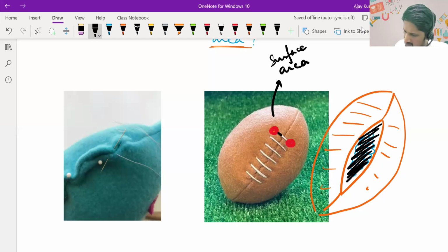So one of them experiences a force this way, the other one experiences force this way. They are being held together by that string, which is used to make those stitches. Same happens with other molecules as well, not just those two. We will just randomly visualize a few. These two particles also are pulled towards each other by the tension in the string. Now we are getting closer to the definition of surface tension. You can consider any two molecules on either side of that line, one molecule on this side and the other on the other side. They'll be held together by the stitches.